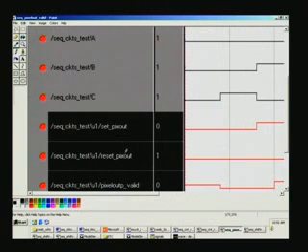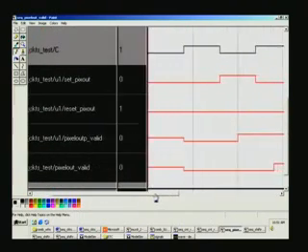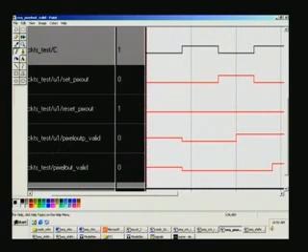And what remains to be done in this is pixel out p valid and pixel out valid, right? And notice that I said pixel out valid is precisely the same output as this, and the only difference is this will happen 1 clock pulse later on, because that's the time I want to pick it up and output saying that the pixel is valid right at this point of time.